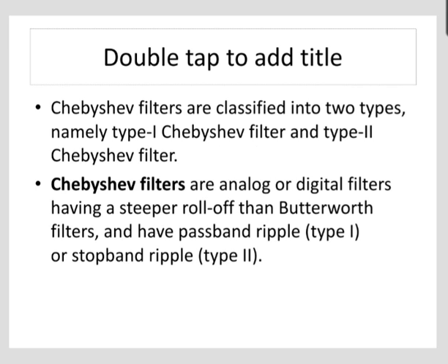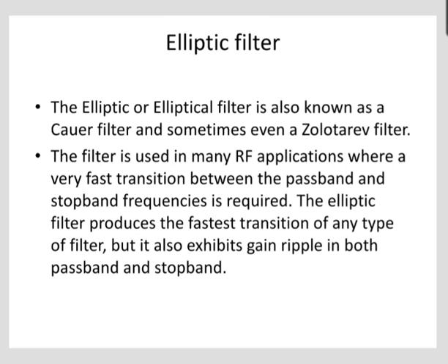The order of this filter is similar to the number of reactive components required for the Chebyshev filter using analog devices. So the amplitude of the ripple of 3 dB results from epsilon equal to 1.